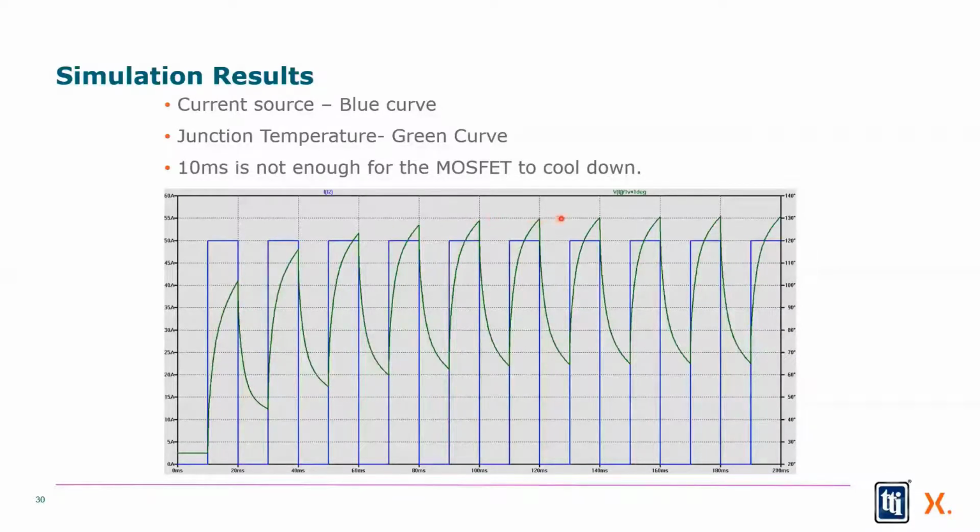So I know that at this rate, it's either going to go off the chart, I'm going to exceed my maximum junction temperature and destroy the part, or it's going to stabilize. In this particular example, once I get enough thermal mass, enough thermal capacity, the part begins to pass the heat out of the heat plate into the circuit board. The circuit board can then be a massive heat sink and it can pull it off. So in this particular simulation, I'm going to max out at about 130 degrees C. In other words, it's a good design. I know that at the beginning, it's going to heat up rapidly. Once it's heated up to a certain point though, that part will not get much hotter. It never goes to that 150, 175 degrees under these conditions. It's a good application. I can get the heat out of the part under the operating conditions that I have.